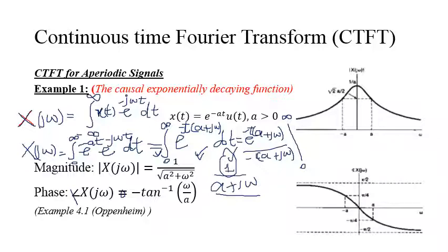So you have 0 minus anything, and that is negative. Now again, you put different values for this one. You understand we have negative values for frequency. So you take omega equals 0 and find the phase. Then omega equals, for example, 1 by a, and you find it. First you find for positive omega, then you take omega equals infinity.